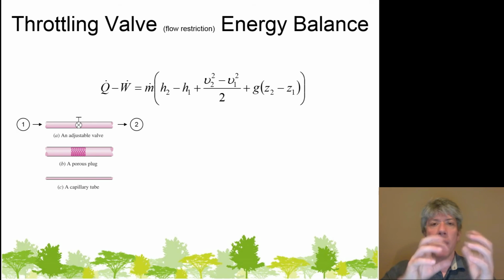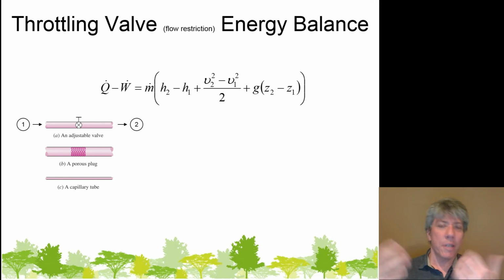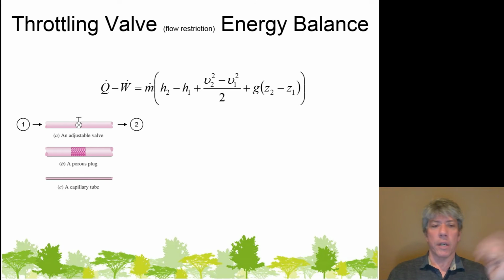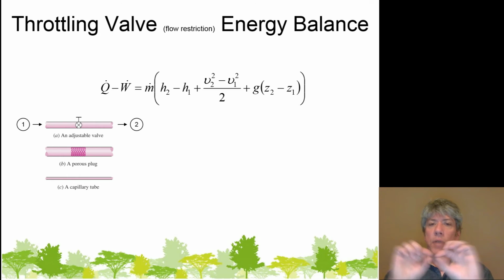But if you take that same high pressure, 110 degree fluid and you expand it with a flow restriction, you let it expand, it will drop its temperature significantly, and so now you can generate really cold fluid, about 50 degrees Fahrenheit or so, that can be used to cool your home. And it's a refrigerant, of course, so you run it through a heat exchanger. But that's really the heart of an air conditioning system, is a throttling valve. There's many different ways to do it. Some air conditioning or cooling systems, for cooling, say, ice in a restaurant, or water at a water fountain, simply use capillary tubes.